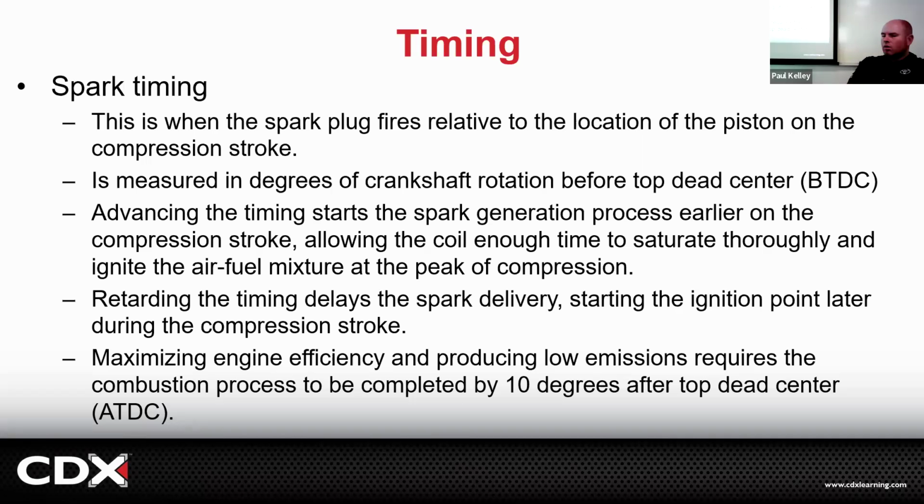That's it. Okay. And then maximizing the engine efficiency generally means we want the combustion process to be completed by 10 degrees after top dead center, right?